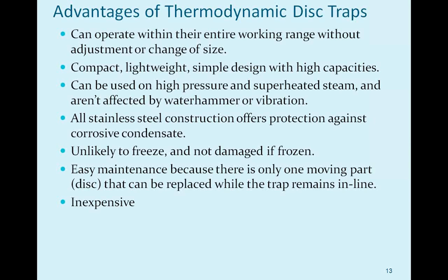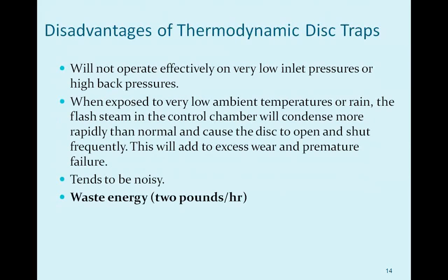There's really only one moving part that needs to be replaced, although what you may see at times, the disc will cause some wear on the orifice from cycling. You know, these will cycle sometimes a couple times a minute depending on the running load that it's seeing. But there are many manufacturers that make a replaceable orifice and disc, so there are ways to address that. And last point, inexpensive. A lot of people don't look at the steam system and the traps as a main concern, and so what we see a lot of is, I just need a 2-inch trap and I want something that's inexpensive, and they are.